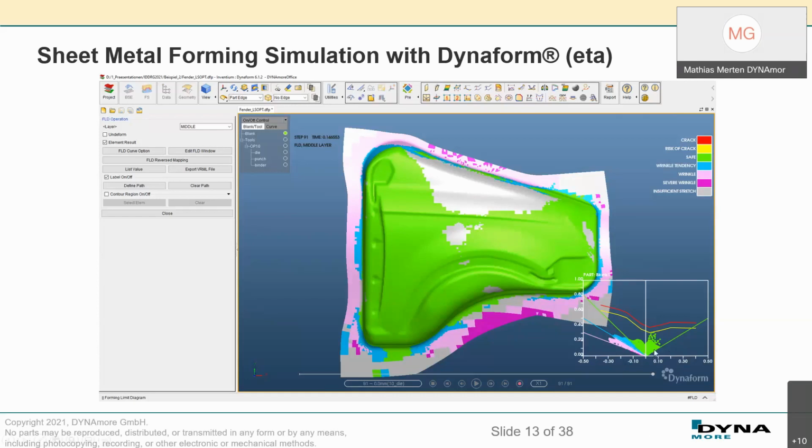For example, how to move this so-called safety margin. Here it stayed at the default, I think it's a 10% shift. But this is also defined, for example, in the standards of big German OEMs, how you have to evaluate your forming results. If you do not have these standards, then you have to rely on your own experience and decide what is a good process. For us, we stick to the defaults, and we would say, okay, this is a green part.